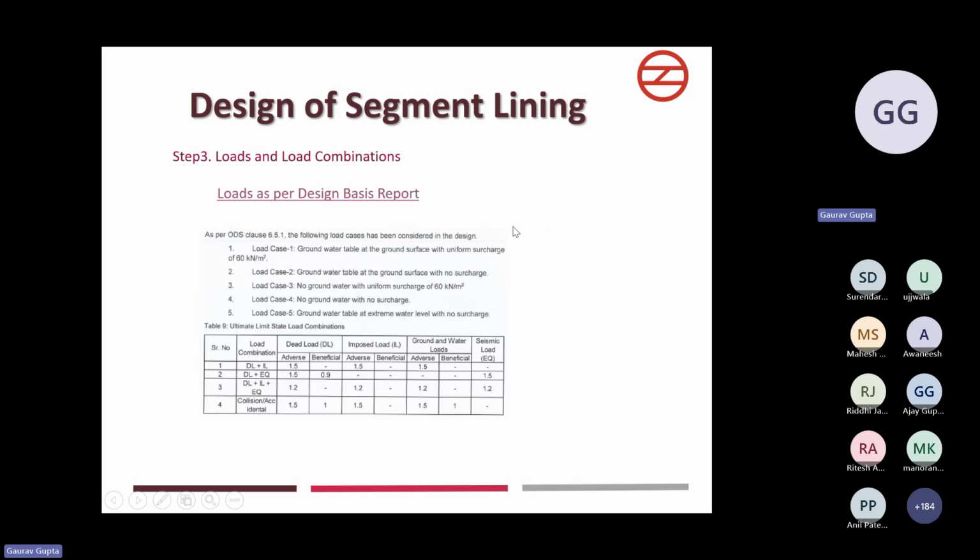In stations also, I think I missed the racking analysis. In racking analysis, what we do, we have to calculate the free field deformation in a structure. It is similar for both a tunnel and for a station closed box structure. And from that maximum deflection, we have to apply a load on the STAAD model, or in tunnel in Plaxis, we can apply the maximum deformation itself in the Plaxis model.